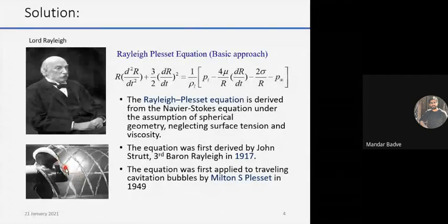So when the velocity increases suddenly, in this region where the velocity is very high, at the tip and behind this blade, a low pressure region gets created, right? And when the propeller turns further, the pressure recovers, and because of that fluctuating pressure field, from low pressure to high pressure and increasing velocity, the vaporous cavities get formed, right? So Lord Rayleigh studied this phenomena, and then he, along with